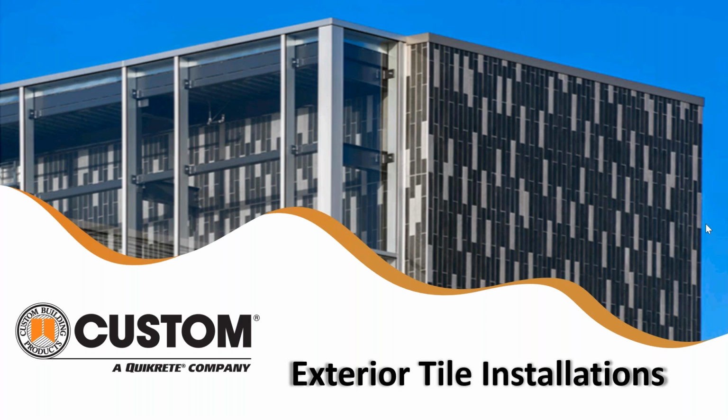For example, the International Building Code says for brittle surfaces, which tile is one of those, out of plane deflection for walls should be no more than L/240. However, the tile industry always recommends a deflection of L/360. And just to complicate things a little bit more, the National Stone Institute says if you're using a natural stone on a stud wall, either metal or wood, they need an L/720 deflection. So it not just becomes responsible to the designer to know which code he's applying, but also which material is going to be applied to that wall. That's just one of several considerations that need to go into that conversation with that specifying entity. So the sooner that those two parties can get together, the better and more successful that installation is going to be.